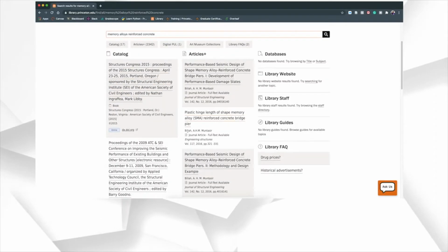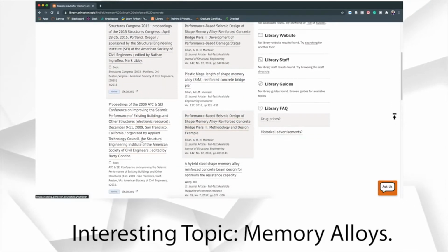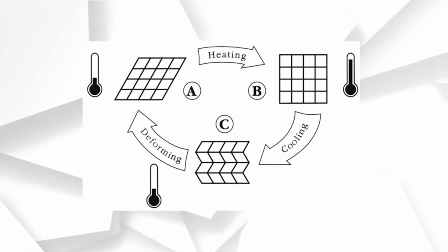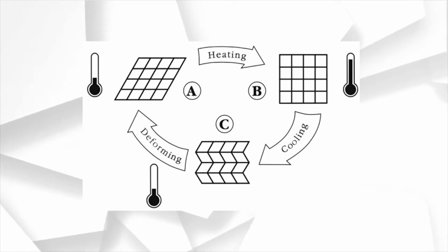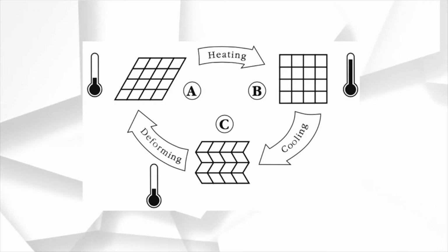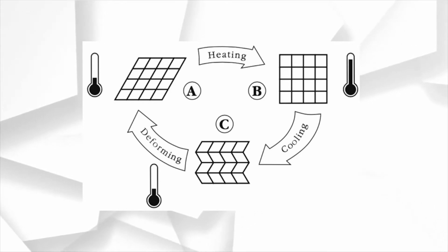By the way, the field of using other metals in reinforced concrete is an active area of research. For example, in seismic areas in California and other states, researchers are trying to use memory alloys that deform well during an earthquake, but then go back to almost the initial shape without excessive permanent deformations. Anyways, this was just a bonus. Let's go back to regular reinforced concrete.